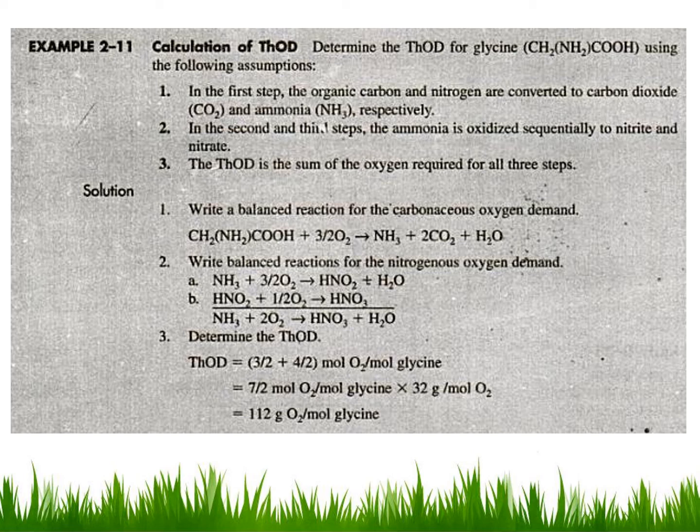So if we have all the molarities and we know the molecular weight and we know exactly what is present in the wastewater, then we can easily develop such equations and we can find out the actual consumption. And at the same time, we can find how much oxygen has been consumed. Similarly, for the nitrogenous BOD, we have these kind of predictions which can determine the oxygen consumption.